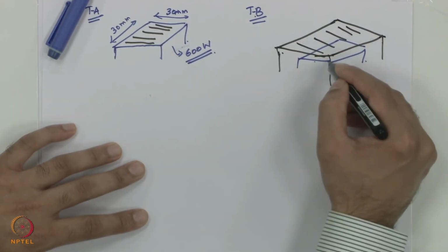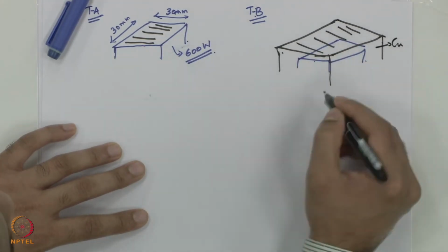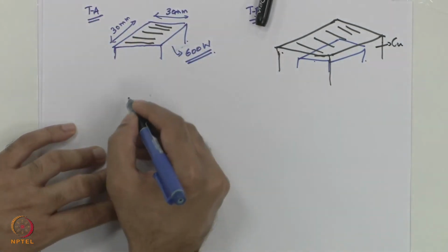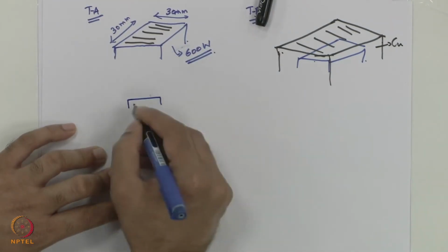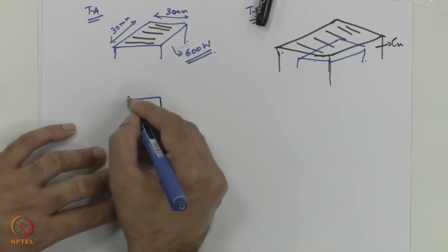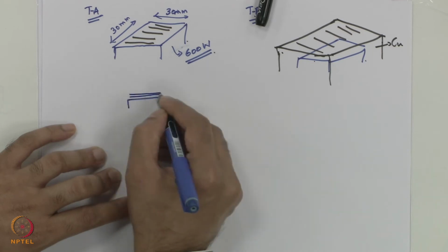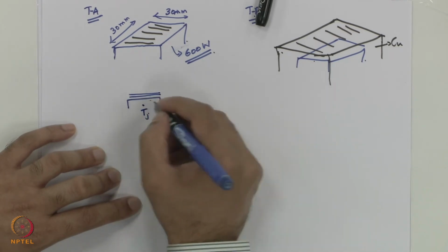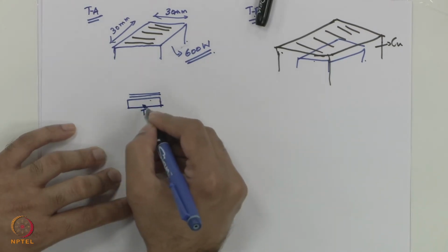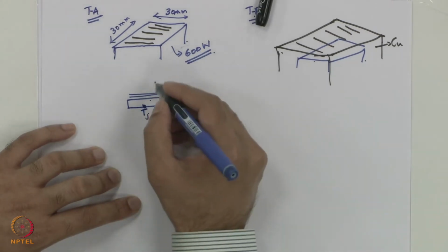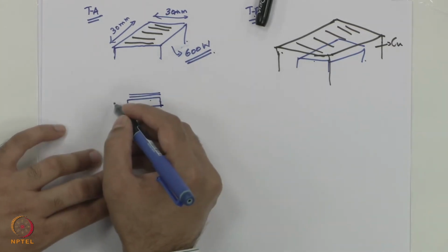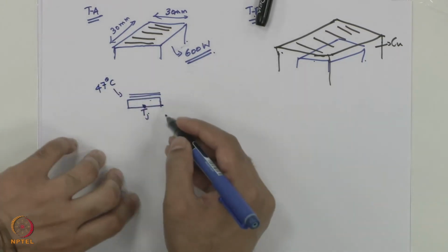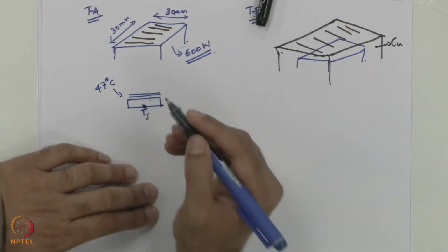So this heat spreader is made of copper, and if we draw a 2D cross section of this, you have a silicon and there are some microchannels laid on this. So this is the junction temperature, T junction, and the liquid water comes in at some 47 degrees Celsius to recover waste heat from this, assuming 100% fin efficiency.